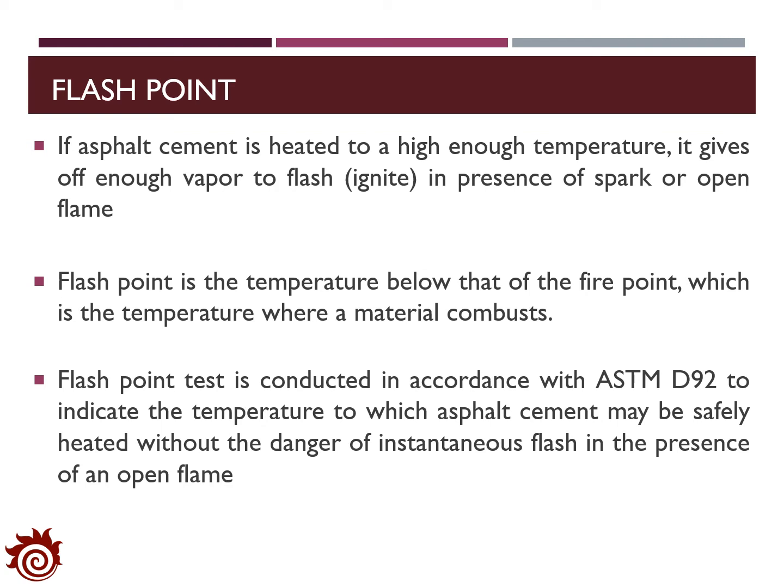The ASTM D92 defines the procedure of the flash point test to identify the temperature at which the asphalt cement may be safely heated without the danger of instantaneous flash in the presence of an open flame.